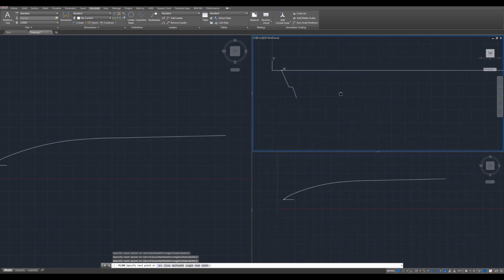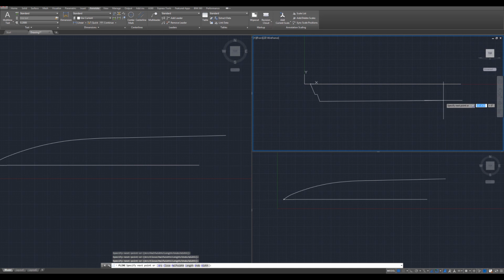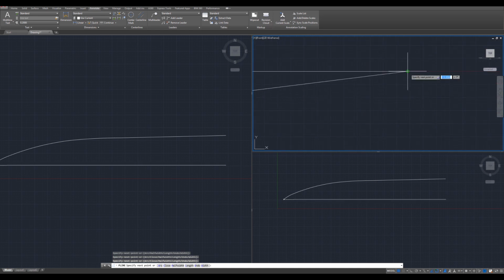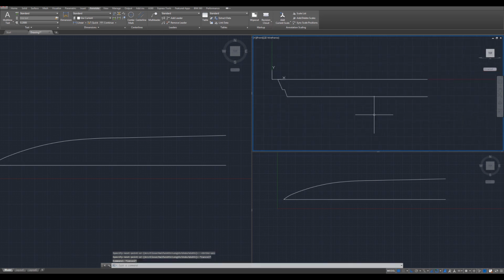And then after that, I'm just going to extend this out up until the end of the yacht. And if I need a reference, you can hover over this point, and it should generate the tracking. And also to help you out, turn on ortho mode, because that usually helps. And then get that tracking onto that point. Okay, and then click once more to get it there.